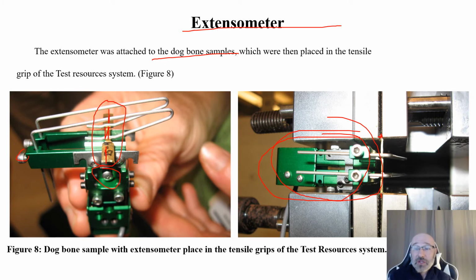If we would have done our research first and known we needed to use an extensometer for tensile testing, and we knew the clearance of the actual dimensions of this, and we wanted to specify this distance here was enough, maybe we would have designed the length of our dog bones a little differently. Luck's out, we were just within tolerance, and this was an existing one that we had in the lab that we could use, and we didn't have to find a specialized custom extensometer or have one made for us.